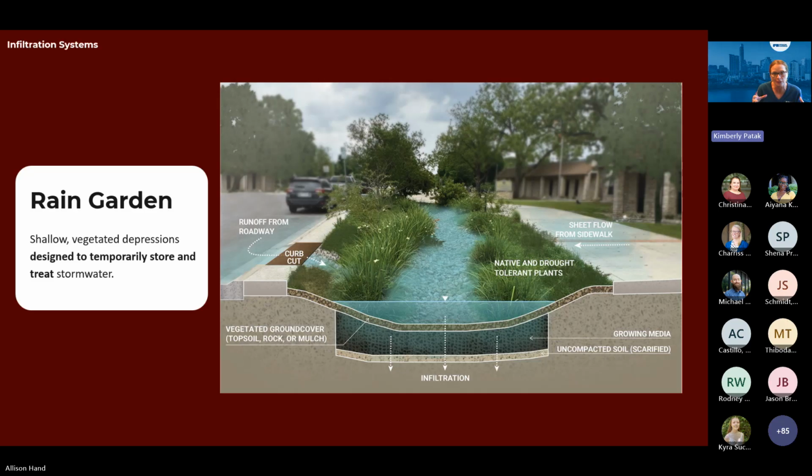They're small, dry areas that trap debris and pollutants from small storms. They're easy to implement along a block side or a parking lot and customizable to the geometry of your site conditions. Depending on your planting palette, they could be planted just with sod if you don't want much maintenance, or densely planted to provide a pollinator garden and an amenity for a neighborhood.